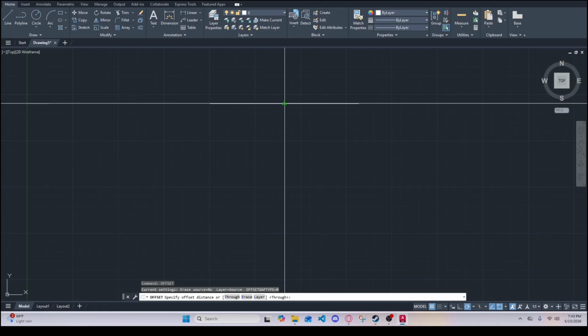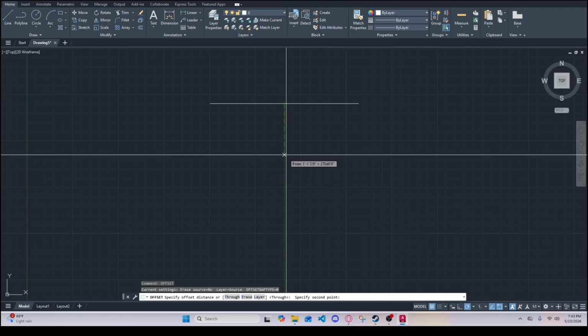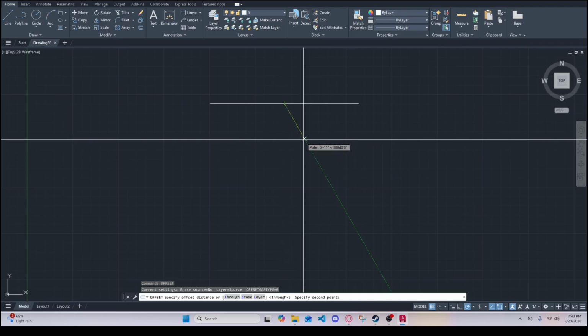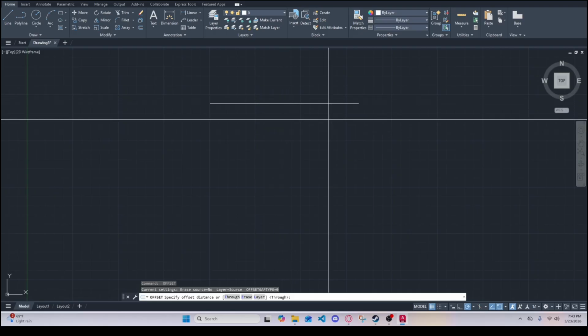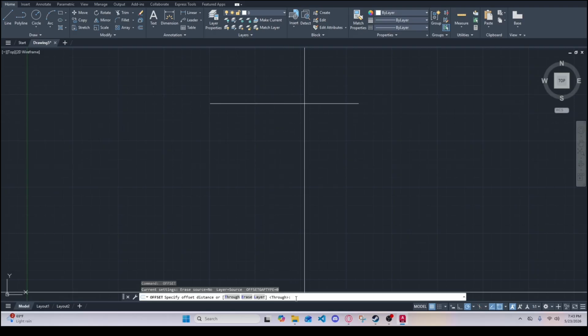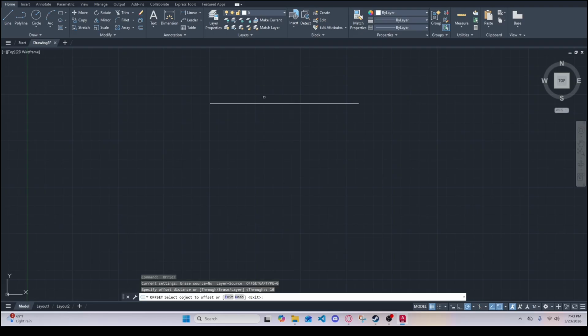So right here, you can either just click and choose a specific distance like this, but if you want to get exactly 1 foot, you'd be here, fighting for your life, just trying to get it, wasting time. Go ahead and exit out of it, type offset again, or just O, space, and enter. You don't have to manually click anything around here. You can just go ahead and type it out in the box. You do want to be very specific. If you're going to be doing 10 inches, just put 10, and that'll be your 10 inches. And spacebar, and that's 10 inches from there.